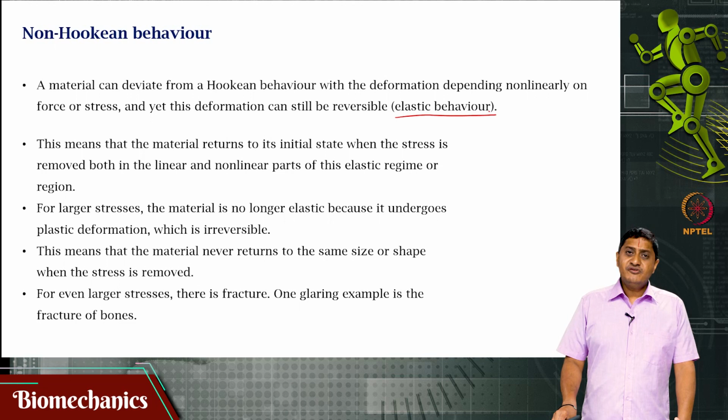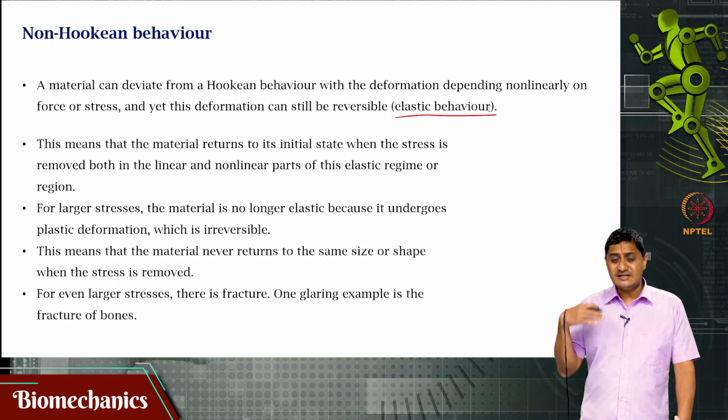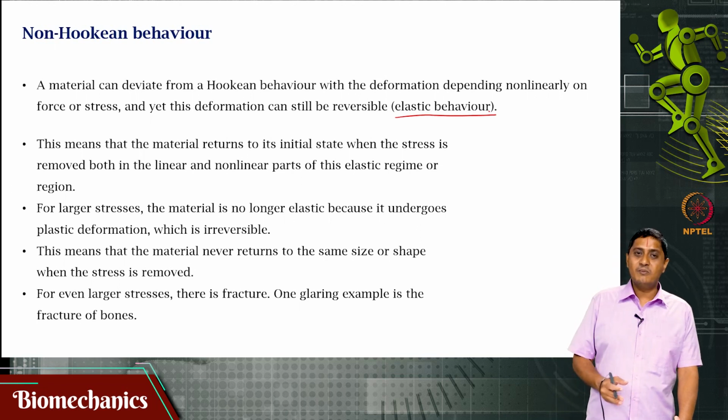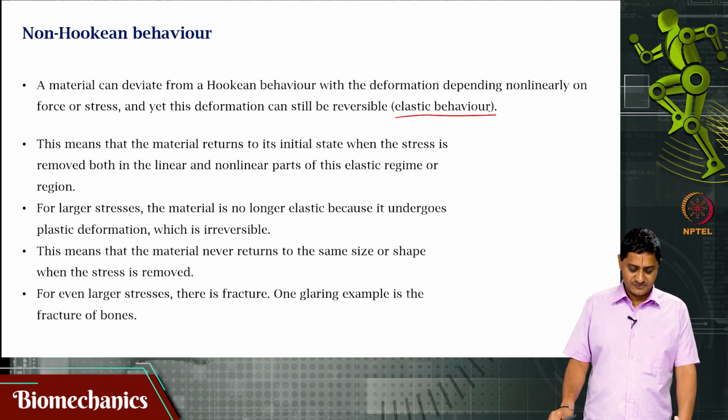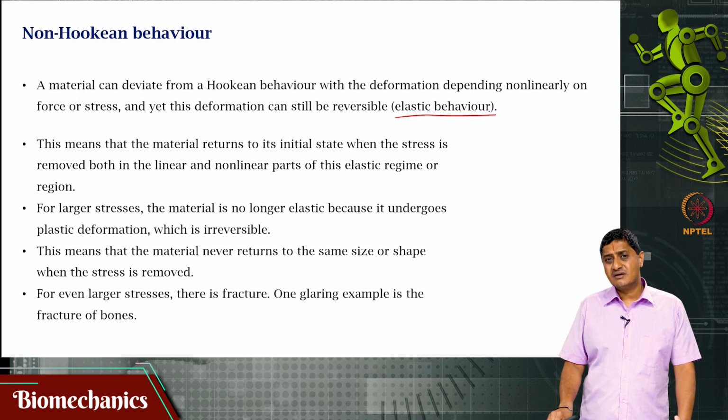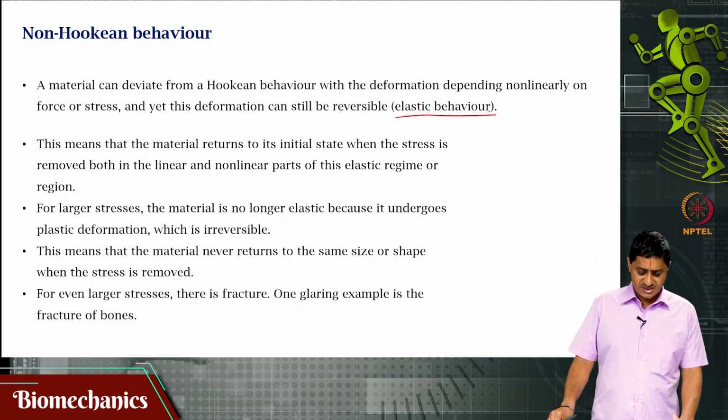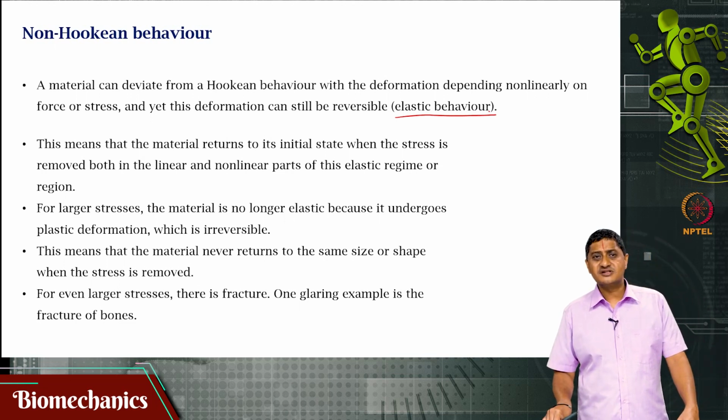Right. But if you keep on applying the force, or if you keep on increasing the stress, the material is no longer elastic, because after some point it reaches its point of maximum elastic yield, or the point at which it can exhibit the last elastic behavior, after which it undergoes a deformation where it will not come back to its original state. That is called plastic deformation, or non-reversible. It is not reversible. Again, that means that it is not going to return back to its original configuration when the stress is removed. If you keep applying the force or stress further, then what happens? The material breaks down, or there is fracture. An example is the fracture of bones.